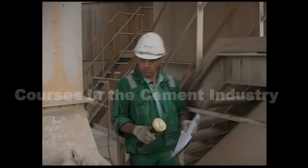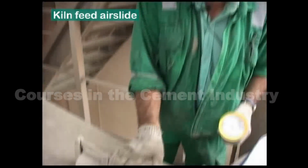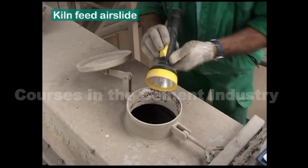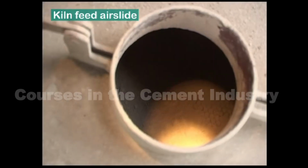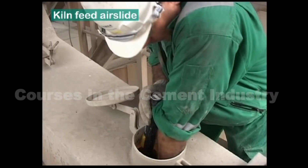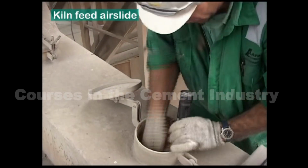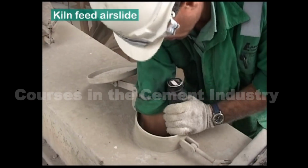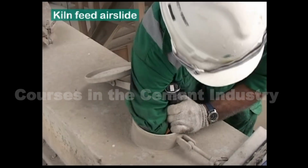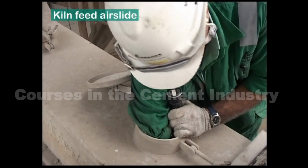See this video. We are going to inspect the kiln feeding air slide. We look at the close inside to see if there is any wear or cracks, especially the fixation at the joint.